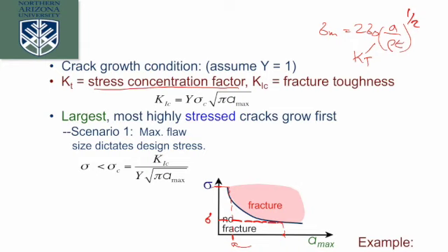And it's a very simple equation. It's related to what we talked about. The overall toughness is related to the material properties. The Y is usually, in this class, we're just going to assume it's 1. This is isotropic. So if you had an anisotropic material, you can change this variable and get a more specific toughness, usually with respect to direction. But in most cases, we're going to assume it's isotropic.